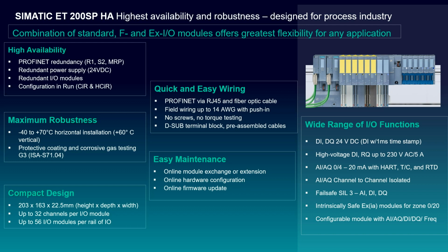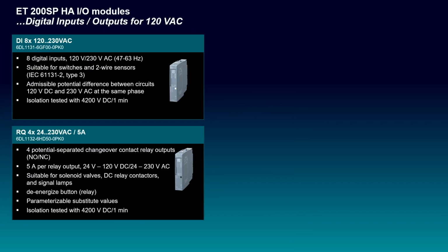We have intrinsically safe solutions that support analog in, analog out, discrete in, and discrete out, as well as, not to be lost in all of the possible I/O modules, we actually have a configurable I/O module that does analog in and analog out, voltage and current, does digital in, digital out, as well as frequency. So as I want to build now to talk a little about MTAs, let's start talking about the AC input and output modules, because that's really where MTAs shine, so to speak.